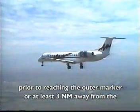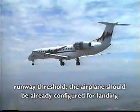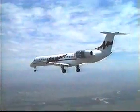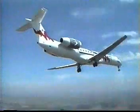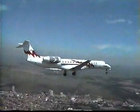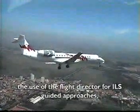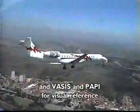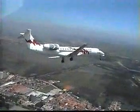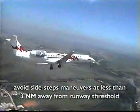Prior to reaching the outer marker, or at least 3 nautical miles away from the runway threshold, the airplane should already be configured for landing in a stable glide path with landing flaps and gear locked down. For a normal glide path of 2.5 to 3 degrees, the resulting rate of descent is about 650 to 800 feet per minute. Rates of descent in excess of 1,000 feet per minute should be avoided. The use of the flight director for ILS-guided approaches and VASIS and PAPI for visual reference is recommended. If possible, avoid sidestep maneuvers at less than 3 nautical miles away from runway threshold.